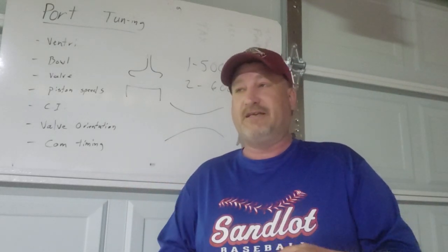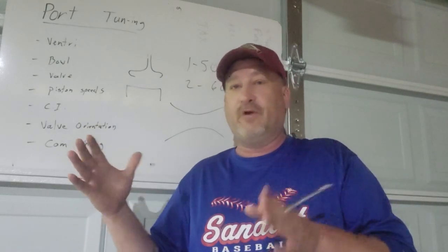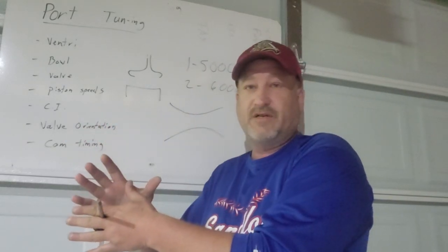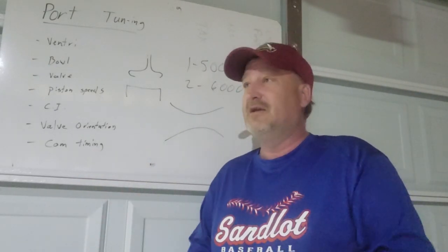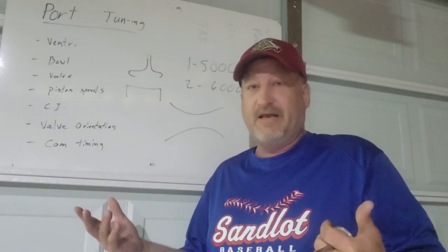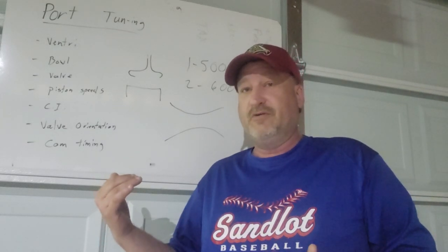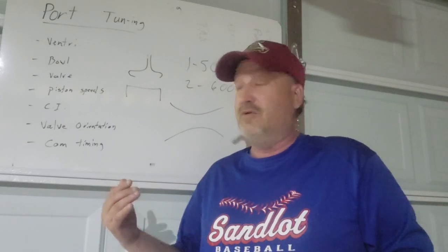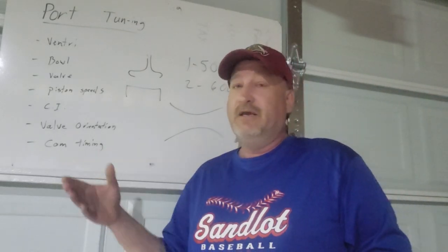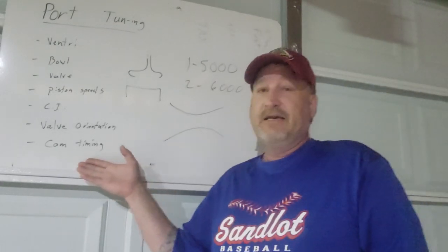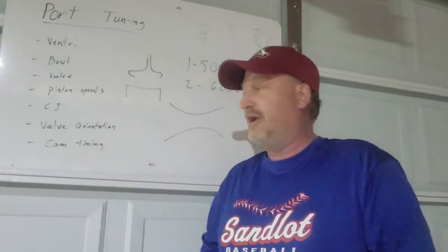So if you're in circle track racing, it was all about that 6,000 to red line portion of the RPM range where all the components were designed to work together. And if you had restrictions within the components, obviously using either factory heads or parts that were authorized by the association, you knew what components you were restricted to or modifications that you were not allowed to do. So the only thing that he gave you to alter was basically the cam timing, even with lift or duration restrictions. Cam timing altered the port tuning in that 6,000 to red line RPM range.